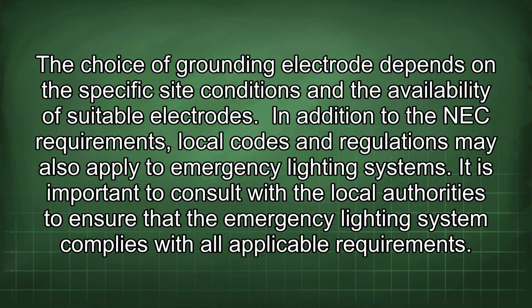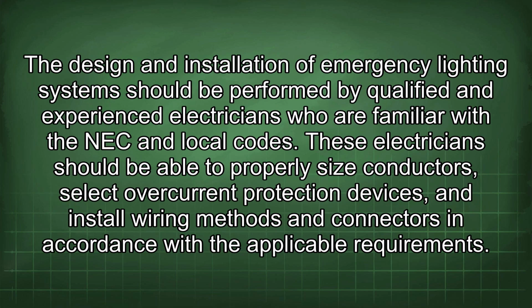It is important to consult with the local authorities to ensure that the emergency lighting system complies with all applicable requirements. The design and installation of emergency lighting systems should be performed by qualified and experienced electricians who are familiar with the NEC and local codes. These electricians should be able to properly size conductors, select overcurrent protection devices, and install wiring methods and connectors in accordance with the applicable requirements.